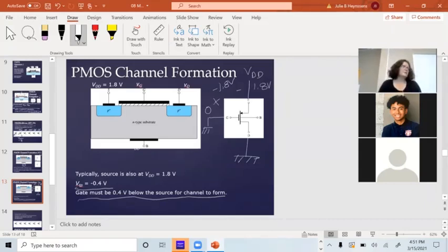So I don't have to put negative voltages in the circuit to use PMOS. I just need to have the gate at a lower voltage than the source. This is the source, even though I tied VDD to it. This is the drain, and then that's the gate. It's just the way you have to hook up PMOS circuits.